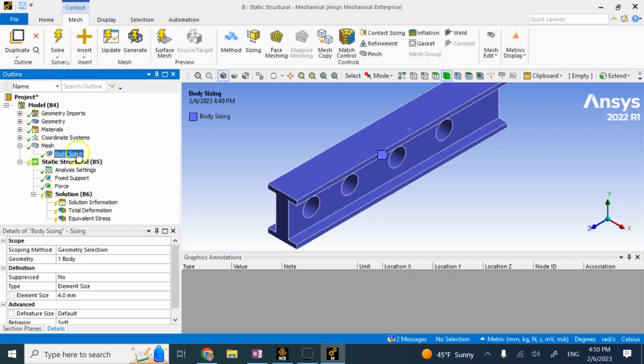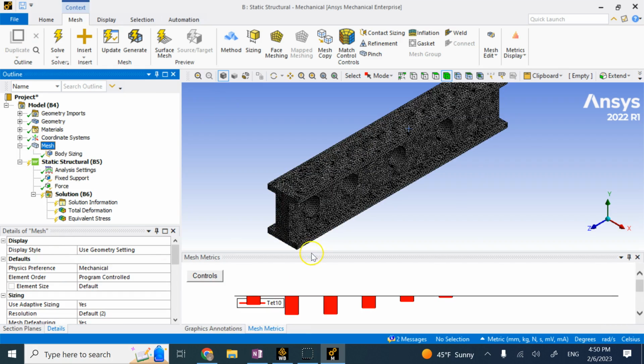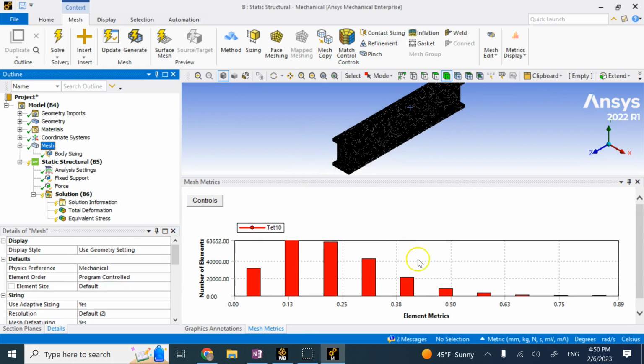And now, if I look at the mesh and look at this distribution here, right, and look at the numbers, you see now the average is 0.22. It was 0.26. So you see, it's not like continuously reducing the size would keep bringing the mesh quality to higher numbers and better with the same rate.